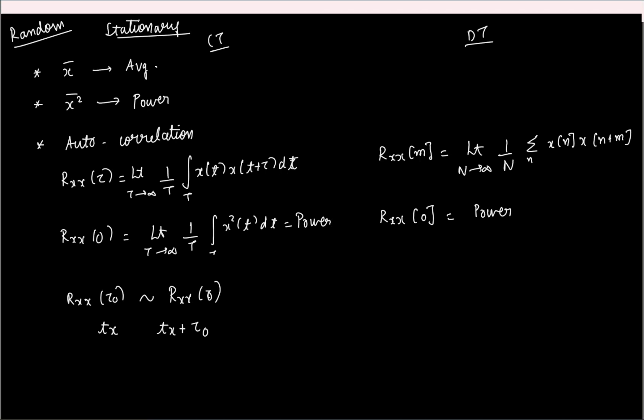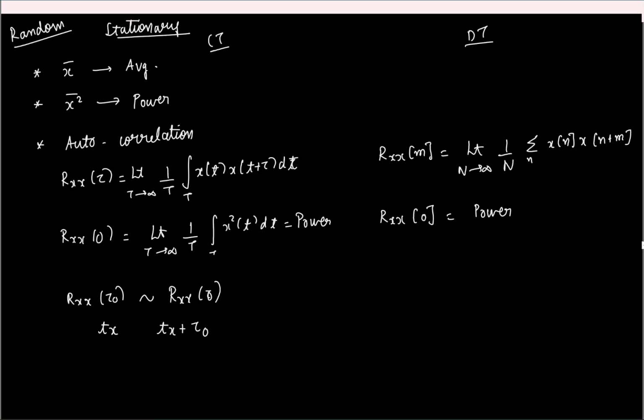Similarly, we'll have statistical measures in the frequency domain also. For deterministic signals, we can look at the Fourier transform or magnitude of the Fourier transform. But for random signals, the amplitude doesn't make sense, right? We are interested in average and power. And for most of the random signals, the average will be 0. So instead of defining Fourier transform, which is an amplitude spectral density, what should be defined properly for this? We are interested in power, so it makes sense to define power spectral density.